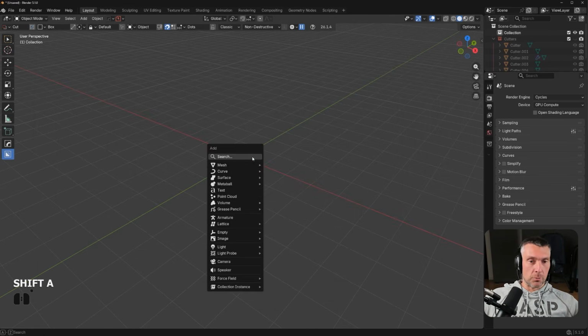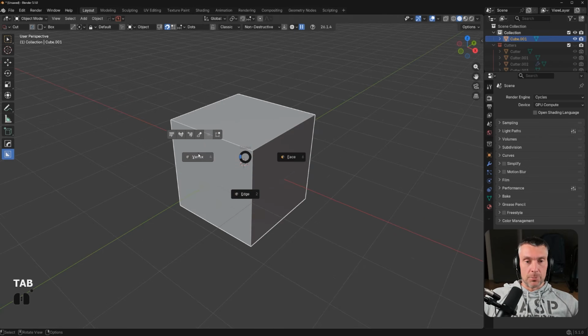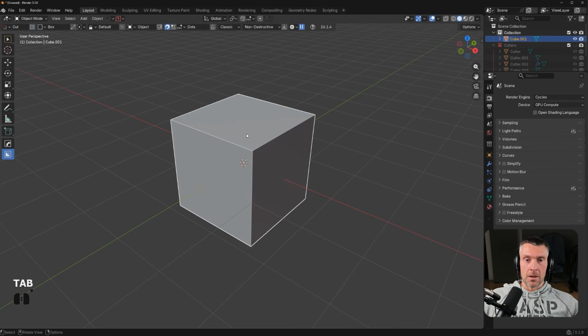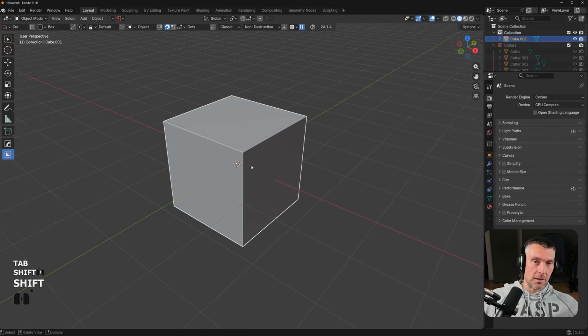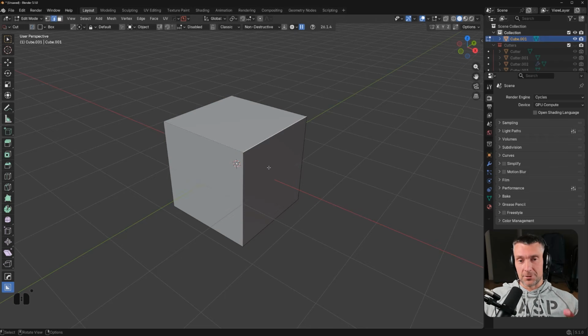First of all, when you work in vanilla Blender and you want to switch between object mode and edit mode, you need to press tab. Then you need to press 1, 2, 3. Fuck that shit. You just press tab and you move your mouse to vertex, edge, face, etc. So if I want to switch between object mode or edit mode, I can just go here and select vert, edge, or face directly. So watch how fast this is. Let's say I want to work on verts. I'll just switch faces to the right, edges to the bottom. Do you see what I mean? It's fast. It's really fast. And that's just one thing.